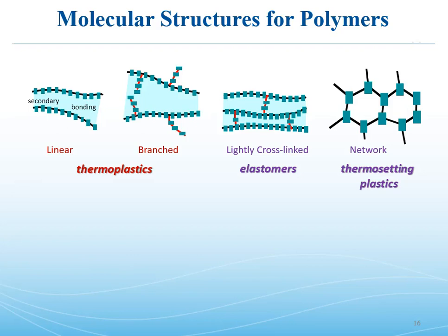And then over on the extreme of chain-to-chain association is going away from chains and actually having a full 3D network. And again, this is the extreme of network thermosets. A lot of your two-part epoxies, again, and many other thermoset materials. But to get those, as you can see, each one of those little rectangles representing a repeat unit has 3 lines coming from it, not 2. So that is a multifunctional repeat unit. That's what's necessary to get a thermoset.